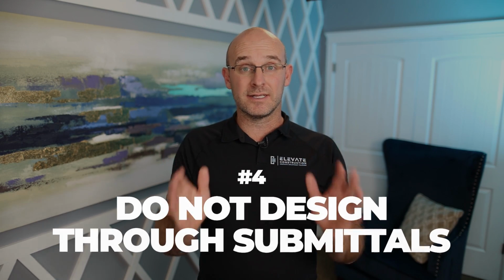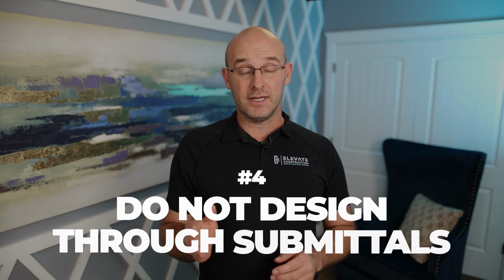And number 4, I'm going to say it again. Yes, this is repetitive. Do not design through submittals. That is so frustrating. Your trade partners signed up to build what's on the contract documents. Make sure that any major changes are documented properly. Make sure we are attempting to get the design documents completed as best as we can before we start construction, and that we are updating them properly as we go. One of the worst things that we can do is to start a project, have one basis, and then start to build something completely different through the submittal process. It's not the way it should work. Let's try and mitigate that as much as we possibly can.